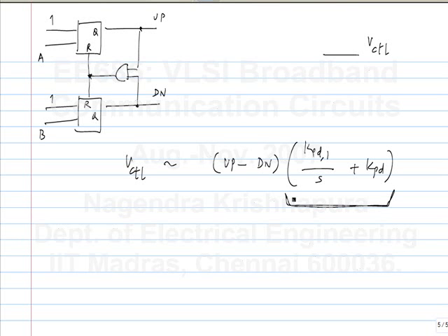What is an integrator like? If you see an integration, what would you use? What component do you need? Yeah, it has to be a current into a capacitor or voltage across an inductor. And inductors are hard to realize, so we generally rule them out. Okay, so the integration in analog circuit design is realized using a current flowing into a capacitor. Okay.